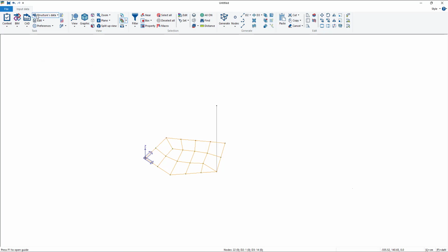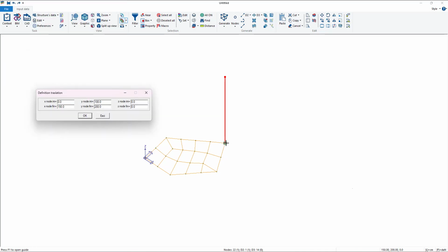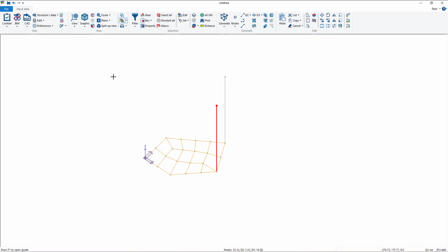Okay, go back. When we use instead copy and move, it is basically the same, so it works in the same way. We can click nodes or we can edit fields on our own. If we go OK, the element is copied and moved. Very simple. Okay, basically these are the main commands. Then you can rotate, mirror, scale. These are quite simple commands.